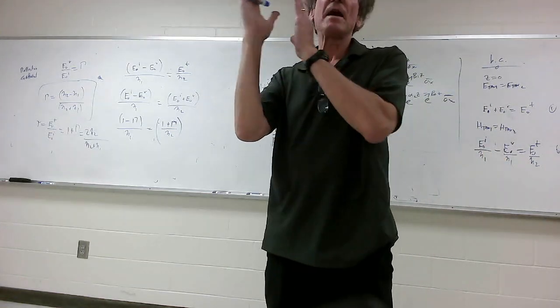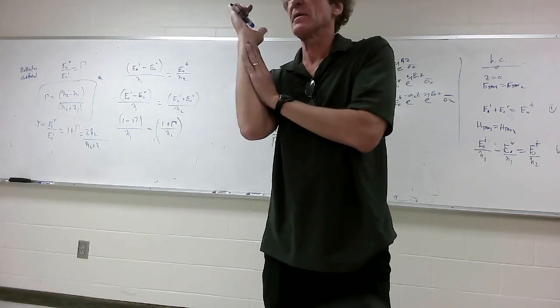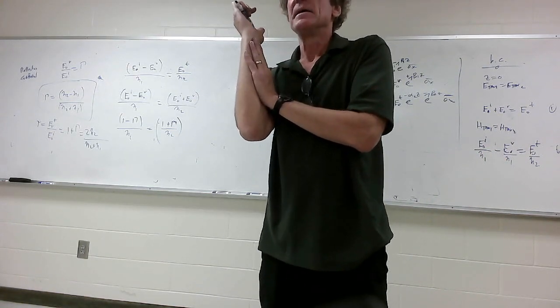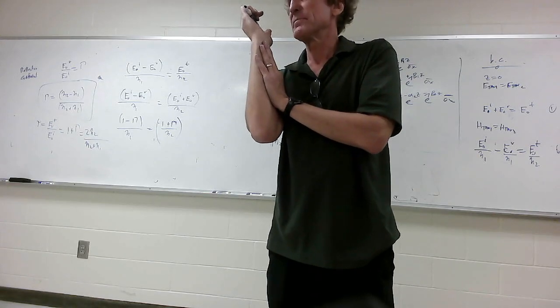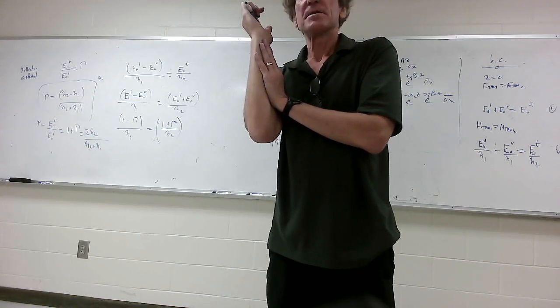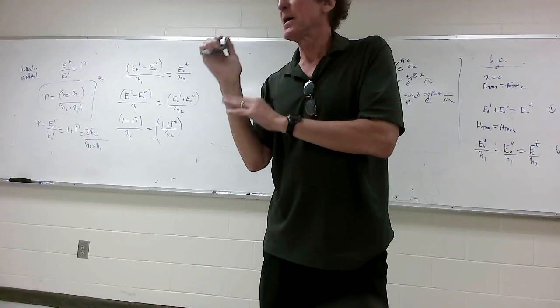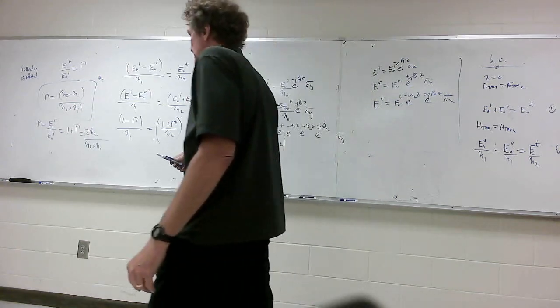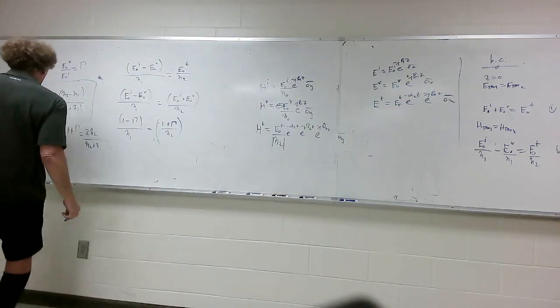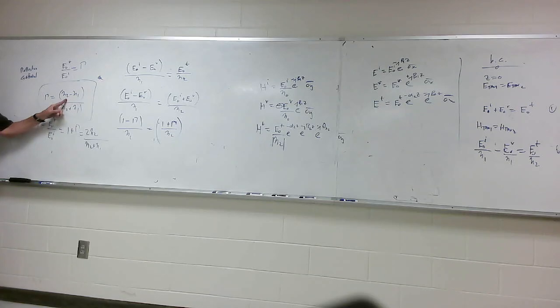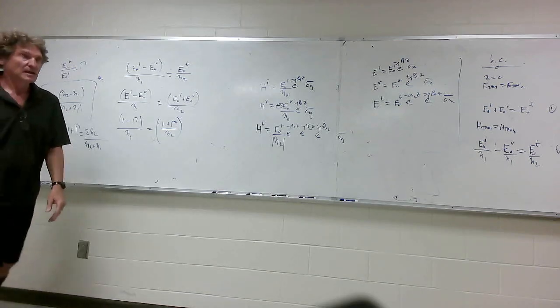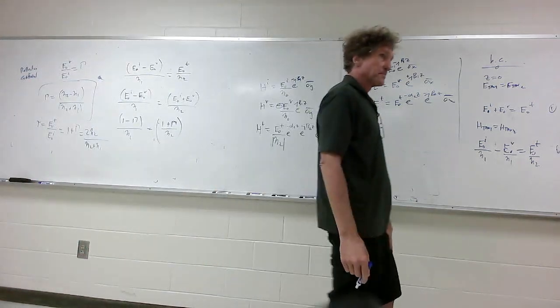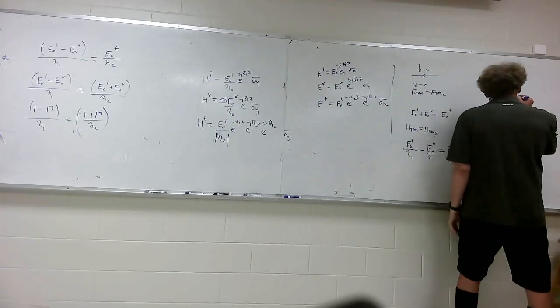Suppose you have a copper plate, conductivity is so high, eta is going to be about 0. Trust me on that. The intrinsic impedance, and you're coming from 120 pi. So what's the reflection coefficient going to be? Well, eta 2 is 0, right? 0 minus eta 1 over 0 plus eta 1 is minus 1. So, very good conductivity, you get minus 1.